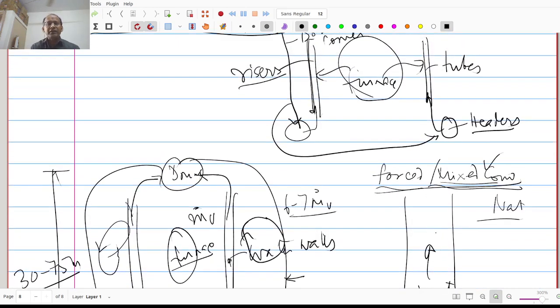And simple boiling of water in a beaker. So you have a burner in a gas stove, and you put a chai ka patila where you want to boil water for tea or boiling water for cooking. Then this typically is nucleate boiling. Initially it is natural convection boiling. There is circulation that happens initially by natural convection, and when the temperature of the heated surface tries to increase further, then you get the nucleate boiling.